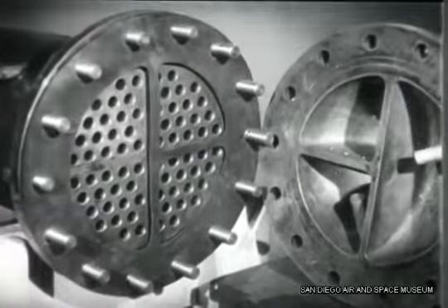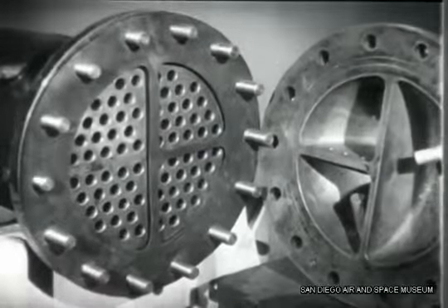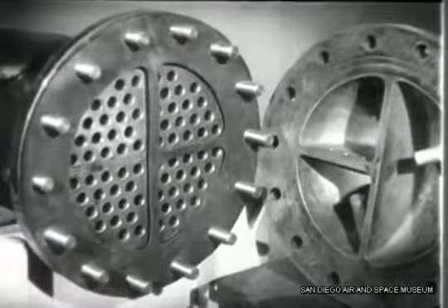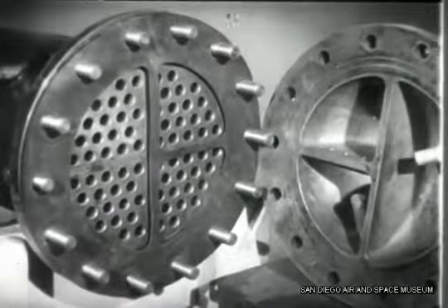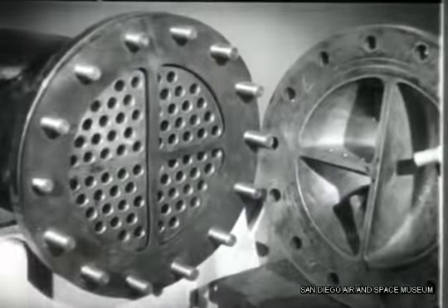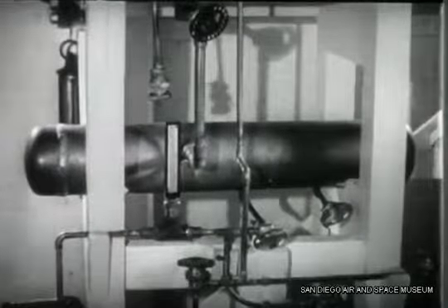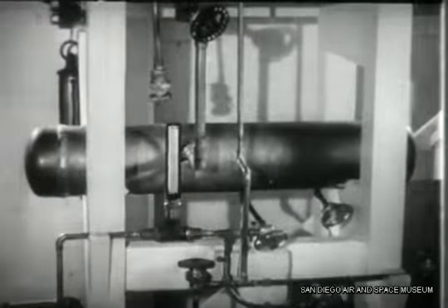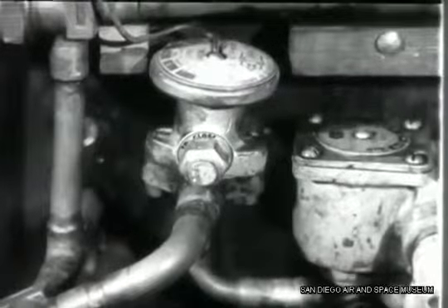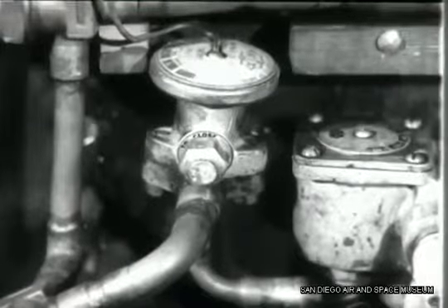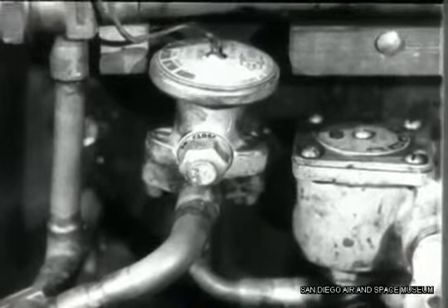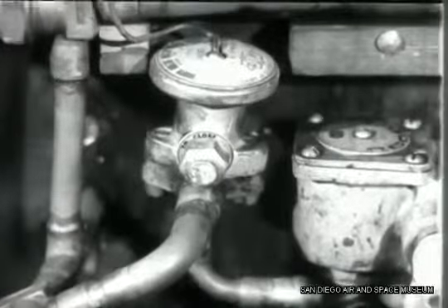Incidentally, as long as Freon is under pressure, it will liquefy even with the seawater found in the tropics, which may be as warm as 85 degrees. The liquid refrigerant then flows into the receiver or storage tank. It then flows back to the thermal expansion valve. Here, the cycle begins all over again.